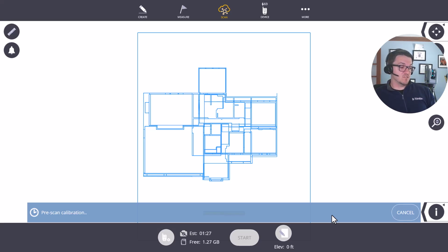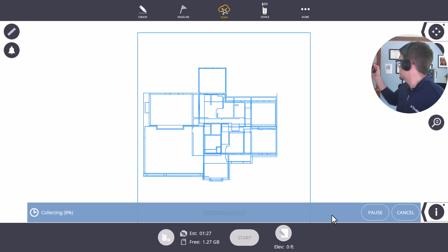So with this first scan, it'll come in. I'm going to show you how to measure from the base of the unit as well as use a reference elevation. You can see a target on the back there. That's about 59 inches above the floor below it. I just measured that with a tape measure, and I want to make sure that it does hit that 59. How do I get there?